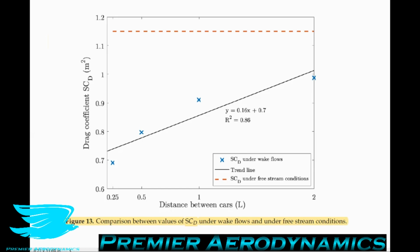So what happens is one car goes behind the other car, and because the drag of the downstream car has now dropped, it can speed up, and then it can just zip around the upstream car much more easily. Now that's on a NASCAR type circuit, which is very straight, and you need straights to do this. In corners, that's not really the case, as we've seen here. The lift area drops, which means that the downforce drops, which means you can't corner as quickly.